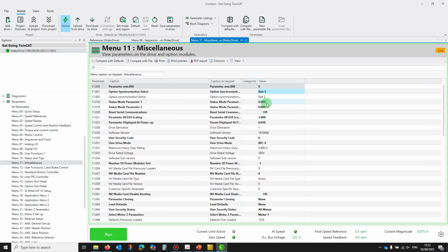So if you want to, and you've got one of the older keypads, you can actually direct this parameter 11 to 18, set that to 1179, and in fact you'll see the name that you've given it on the display, which if you leave it as the default, which is the EtherCAT slave node number, it will display the whole node number on there, and that's actually quite a useful thing when you're dealing with a big network and drives with displays. You can actually go ahead and view the name that's been given.